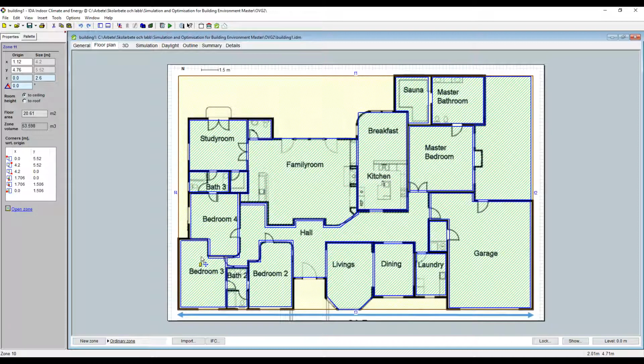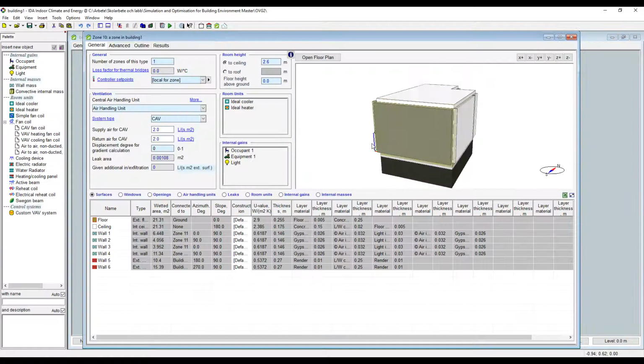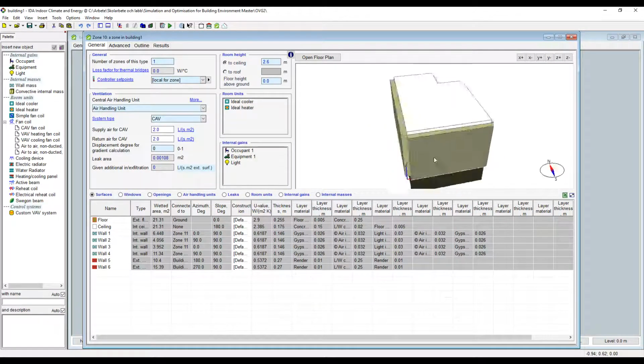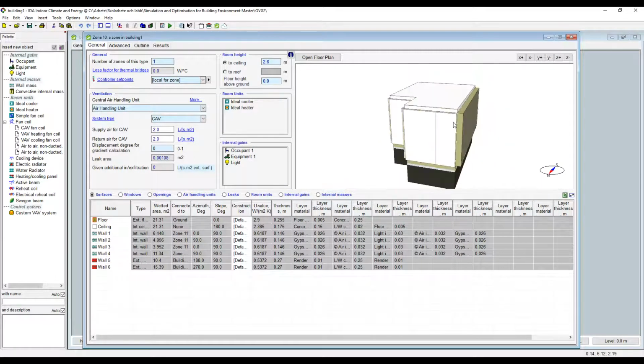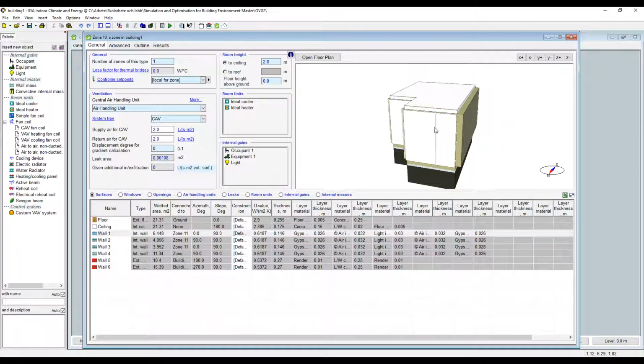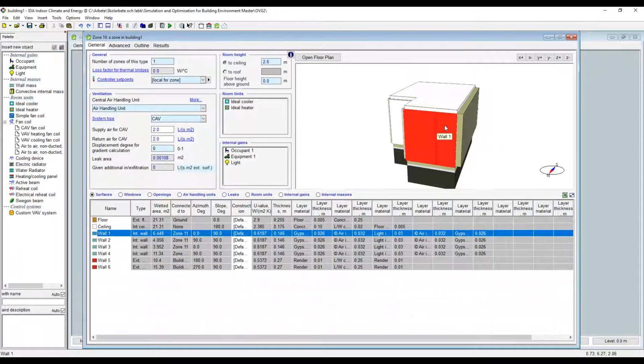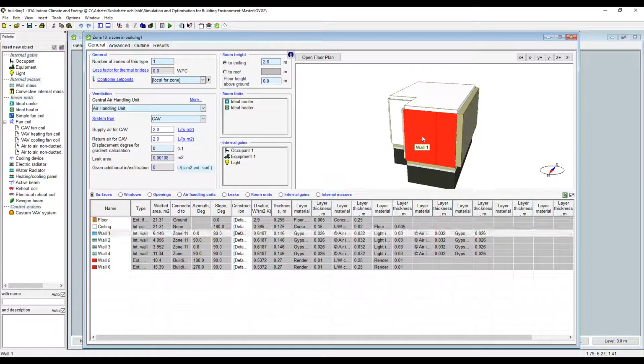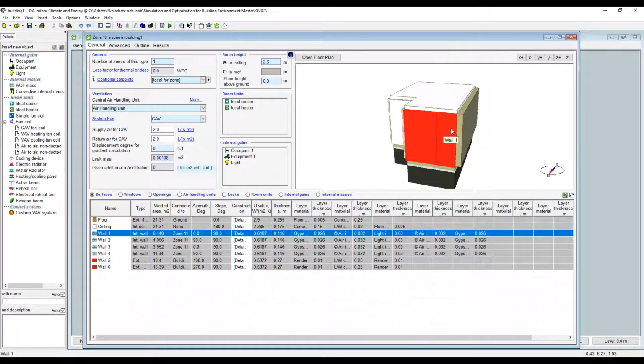So this case is a little bit special. As you can see, if I double click on this, I cannot actually choose this part of the building and only change that. So what I need to do is split this wall into two walls so that I can actually choose what I want on this side and what I want on the other side.